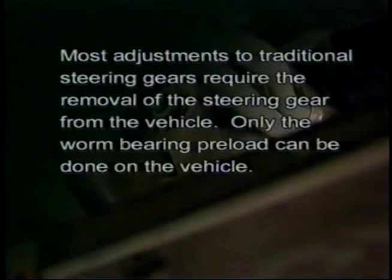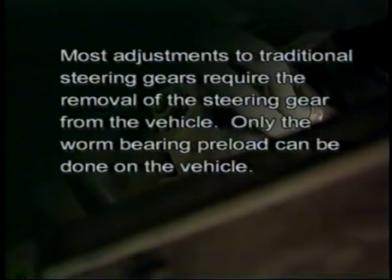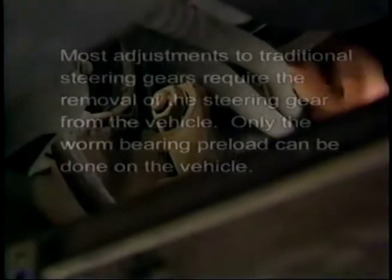Most adjustments to traditional steering gears require the removal of the steering gear from the vehicle. Only the worm-bearing preload can be done on the vehicle. When removing the steering gear, always mark the relationship of the pitman arm to the sector shaft, and always use the proper puller to remove the pitman arm.